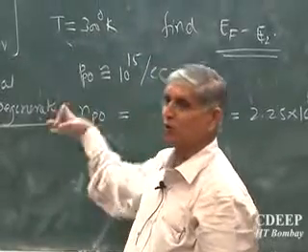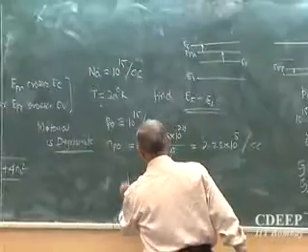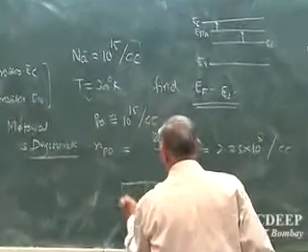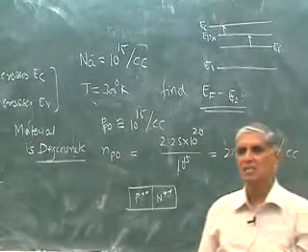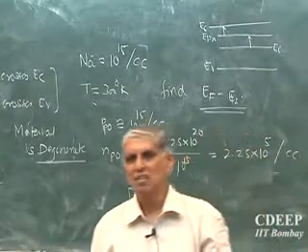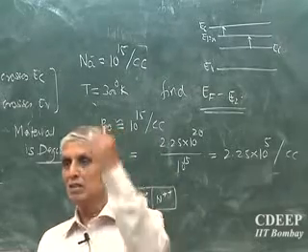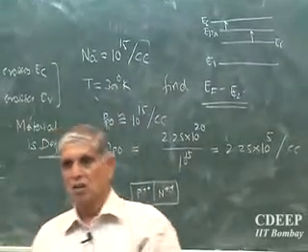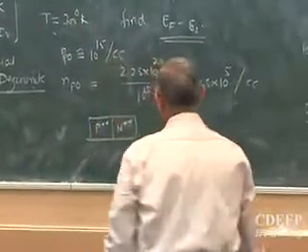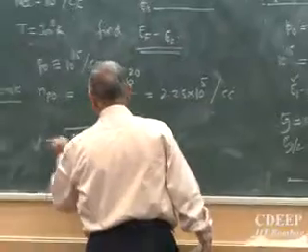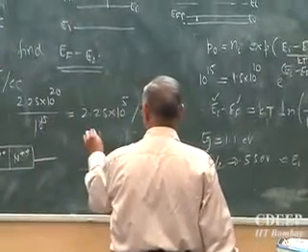So why did I show you this? There is a device, we call it, which is heavily doped. One side is heavily doped n-type, the other side heavily doped p-type. Heavily means such that they cross both bands easily. These are degenerate junctions. Now in this case, this diode, a normal diode, has a characteristic something like this.